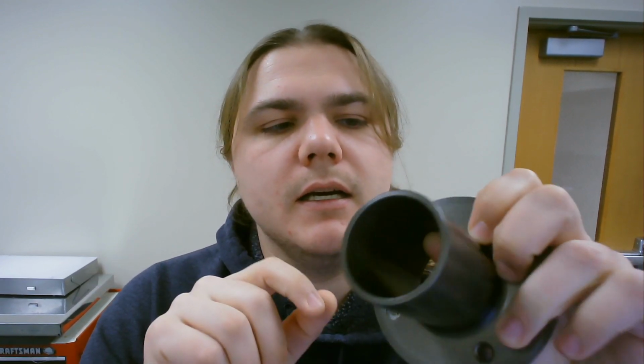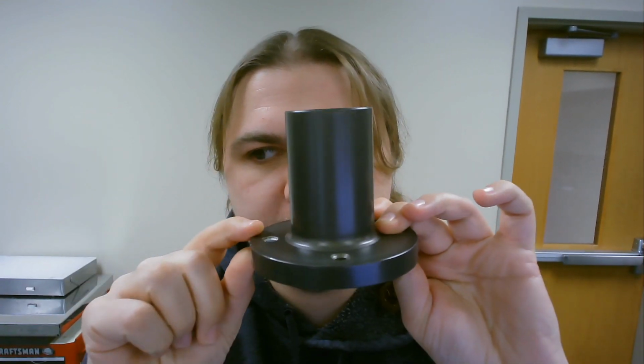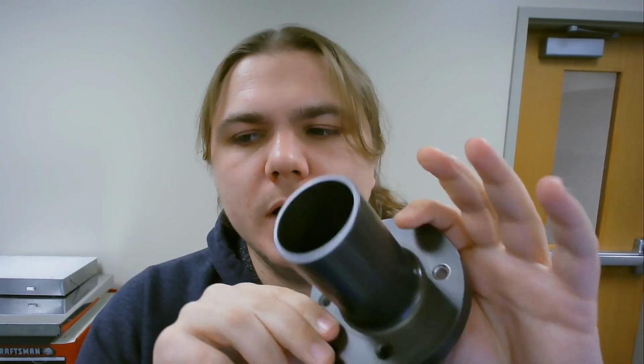So when I'm designing the model of this part, I would have a dimension for the inner diameter, and then instead of also doing a diameter dimension for the outside diameter, I would simply add a thickness to the outside diameter from the inside diameter. So whenever the interior diameter gets bigger or smaller, the thickness is maintained. The overall height, that one would be pretty simple. Overall height and maybe the thickness of the flange here, and that's all it would be.